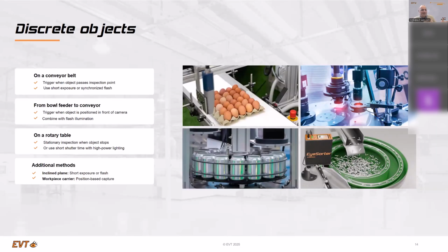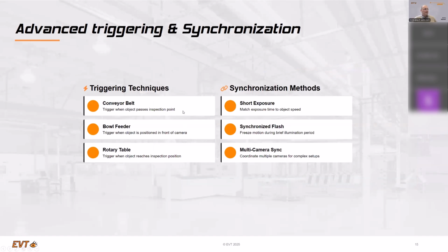But more important is that the measurement, which you may also have to do for quality control, needs a perfect contrast. And a perfect contrast is, in this case, a through light situation where the light is on the back side, on the opposite side of the camera. With a perfect contrast, you have a perfect measurement. So getting the perfect light means how to capture the image perfectly.